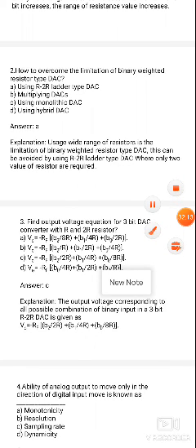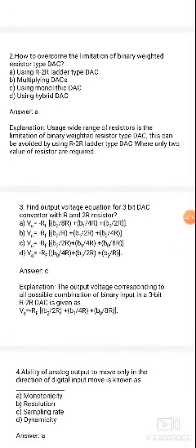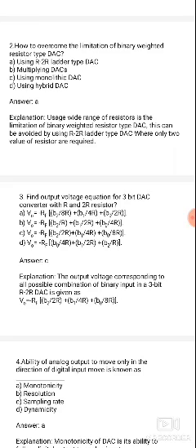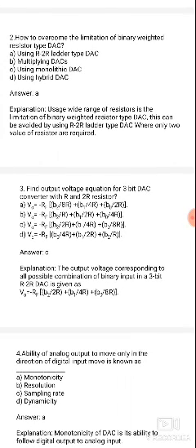In the binary weighted resistor, the main disadvantage is that it depends on the binary weights of the resistors. To overcome this main disadvantage, we go for the R-2R ladder. That is how to overcome the limitation of the binary weighted resistor: by using the R-2R ladder method. Why? Because for digital to analog conversion there are only 2 methods, binary weighted and R-2R ladder network. The binary weighted ladder resistor has limitations. It depends on resistance value. If the number of bits is increased, it is more difficult to maintain the circuit, and the circuit complexity increases.